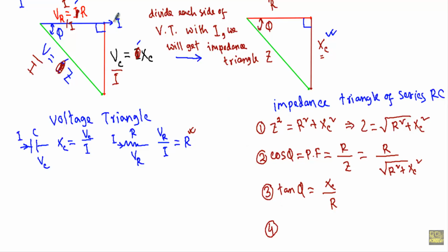See here, if we take the current phasor in this direction, this will be our phasor voltage. This indicates that our phasor current leads V by phi. So in a capacitive circuit, current I leads V by an angle phi, and in case of a pure capacitor, V lags or I leads by 90 degree.